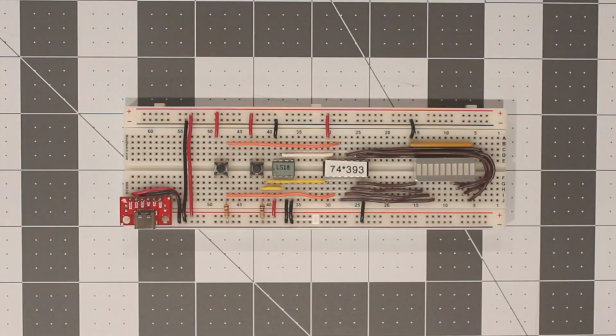To test the LogiSwitch IC and demonstrate the results of debouncing, we will push the button 15 times. As before, the goal is to trigger the counter 15 times and set all 4 counter bits high.